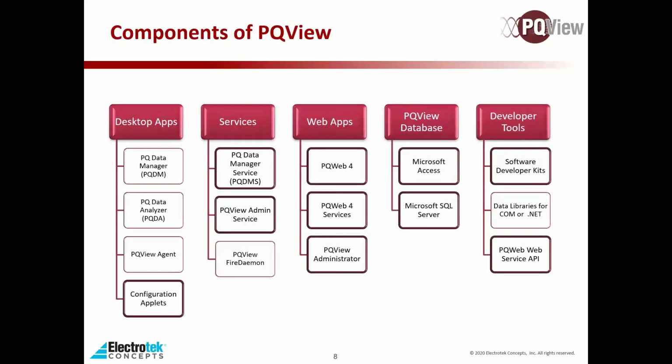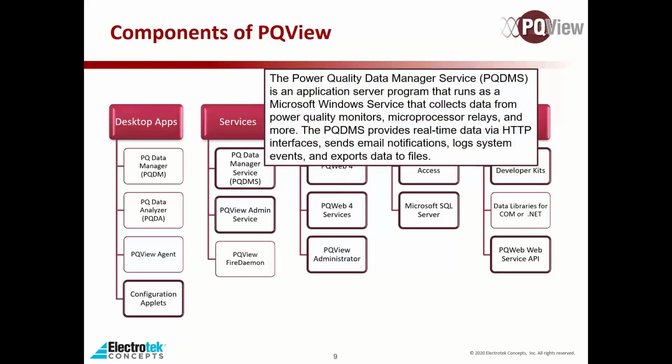So PQView has quite a few software components, and I just want to highlight a few of them here, because these are the ones that we're going to be going into more detail on further on in the presentation. The PQDMS is what provides our data aggregator functionality. This is what's actually communicating with the devices in the field, bringing that data, putting it into the PQView database. This is also the service that would be sending out notifications and providing real-time data.